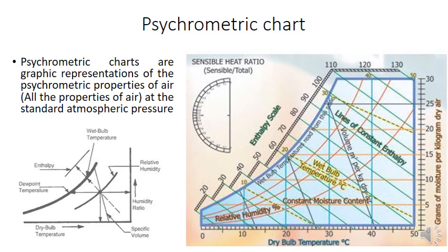If you switch over to this figure, which has simple black and white lines on the left side, it will give you some idea. So this is enthalpy values, then humidity ratio, dry bulb temperature, and some specific volume lines as well. This is the wet bulb temperature line and the dew point temperature line. Inclined curved lines parallel to the enthalpy scale are the dew point temperature lines. Once you go to the actual psychrometric chart, things will be clear.